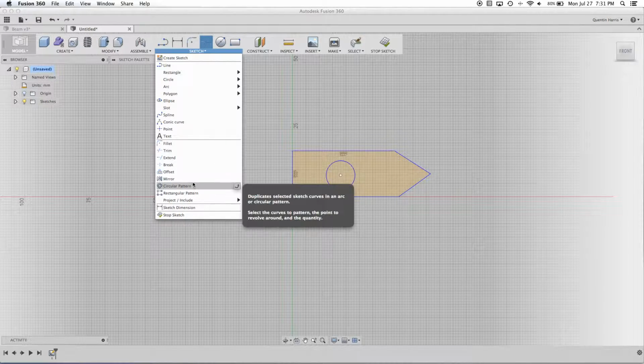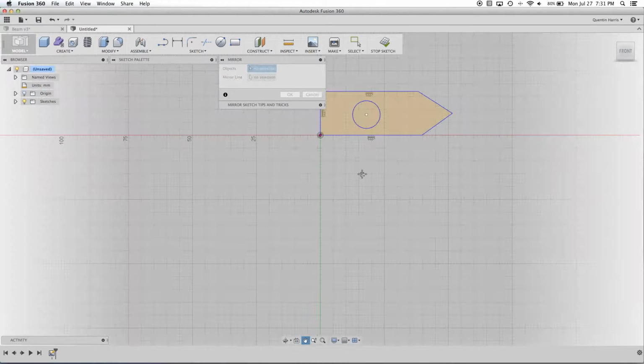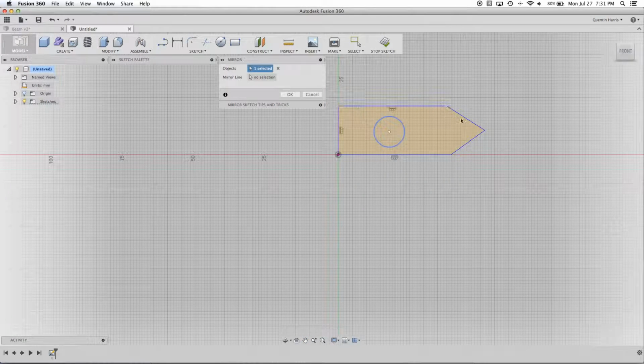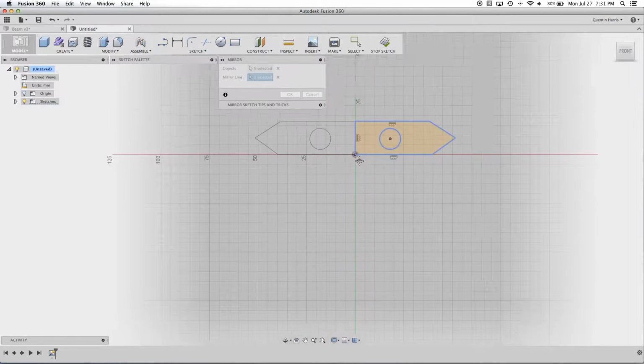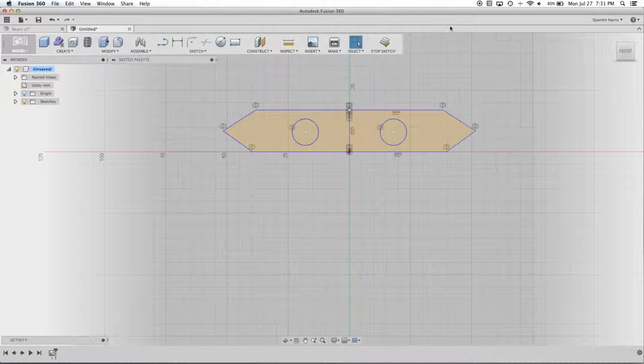It's under Sketch, and you can go down to Mirror, select your objects, which is just the lines that you're going to be using. And when you do this, you should use dimensions and constraints for all parts of your sketch so that nothing's moving around, because if not, then they're going to be moving around on your mirrored object as well. So I would just go ahead and recommend to constrain and define your first object before mirroring it, and then go ahead and use the mirror tool.